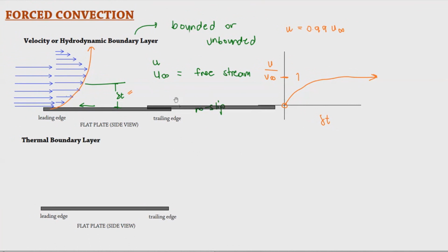No, not exponential, but increasing. So if we add another boundary here, it will not look like this, but like parabolic. That is very important, because if you're asked what the velocity profile of a fluid that enters a pipe is, you would say it's parabolic in nature. And where do you think you'll be finding the maximum velocity? The maximum velocity of that fluid will always be at the center line region of the pipe. At the very center of that pipe, you would see that the velocity is at its highest.